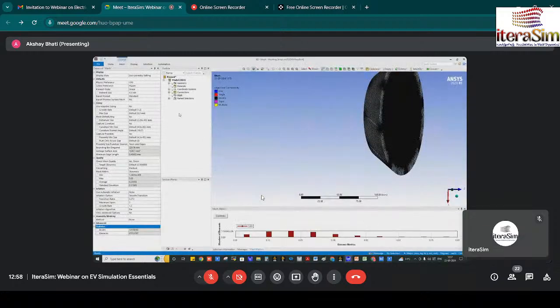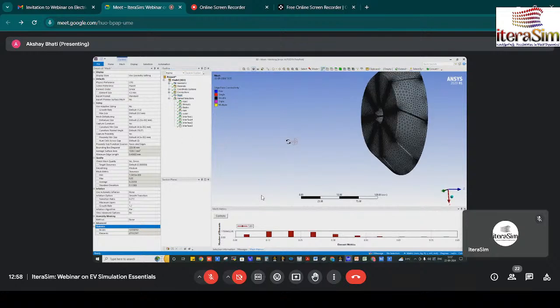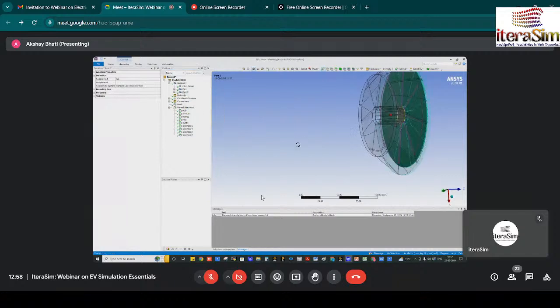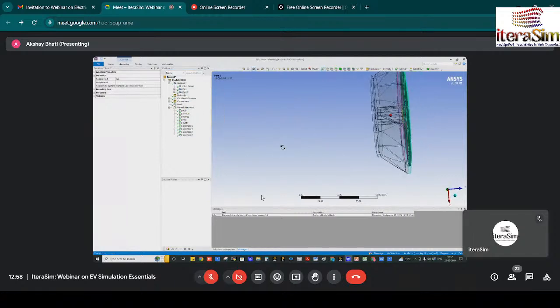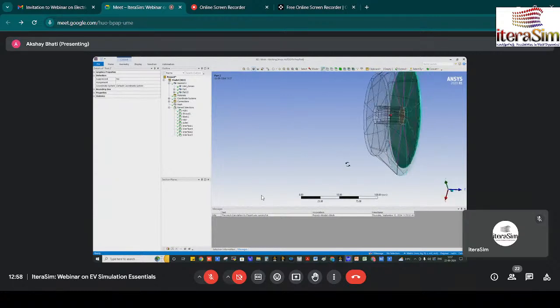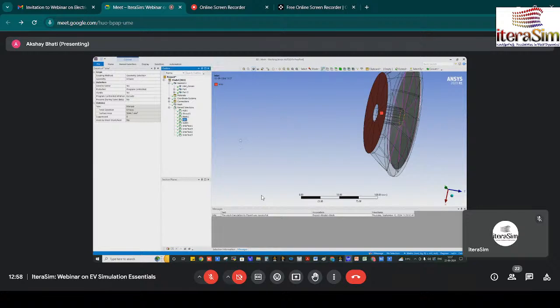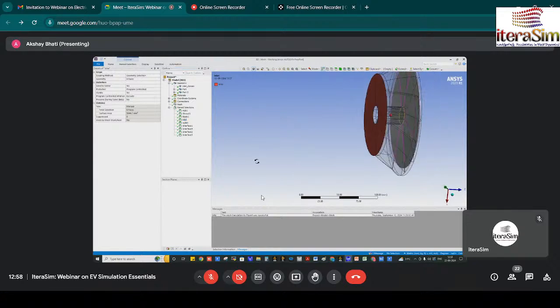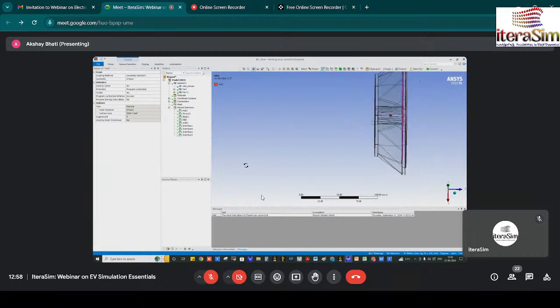And in that meshing I want to discuss one thing also, that you have three bodies. First, show all bodies, because it is hidden. Show body, and part two, show body. In that one, first is the inlet. I also provide a bend support over there. So here you check that inlet is the air inlet, from that end the fan would suck the air.